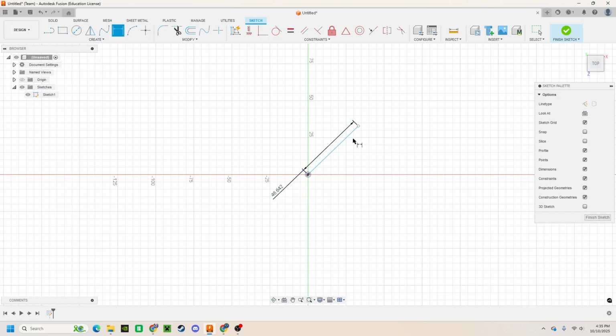Another thing that you can do is that you can select the distance in which it was measured, whether it be in the X or Y directions. So if you press on the dimension and delete, you can select it in the Y direction or that was the X, or in the Y. You can also put lines on other points.